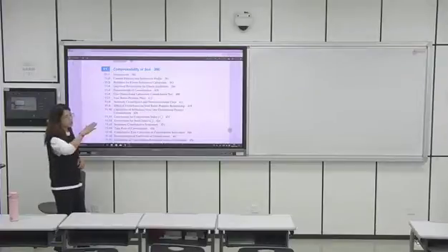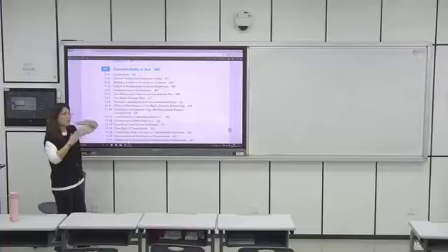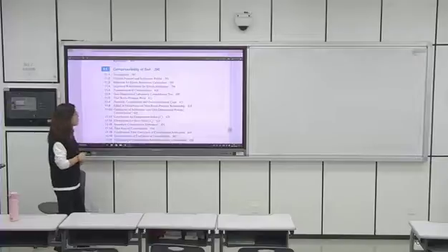We say that this curve has 2 parts. One is flat and another is steep. The slope of these 2 parts gives us the swelling index and compressibility index. And the tipping point, the corresponding pressure of the tipping point, actually gives us the pre-consolidation pressure.